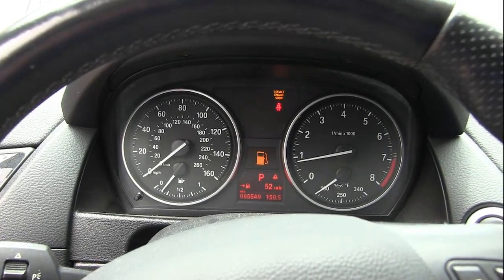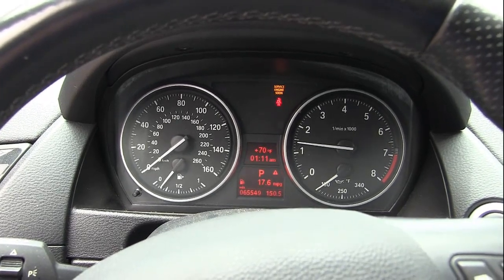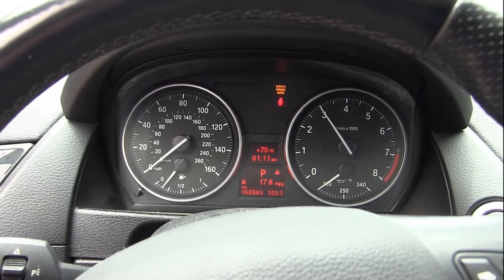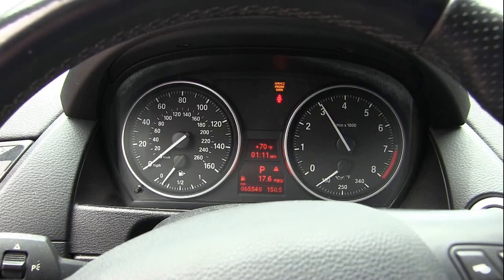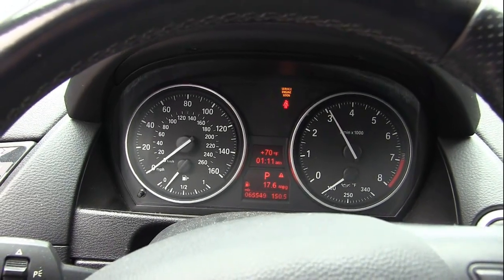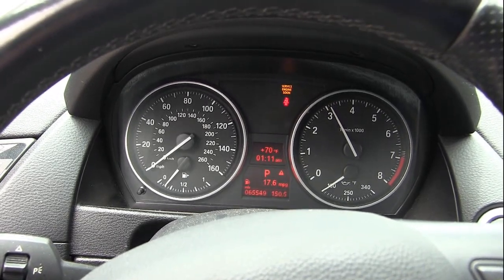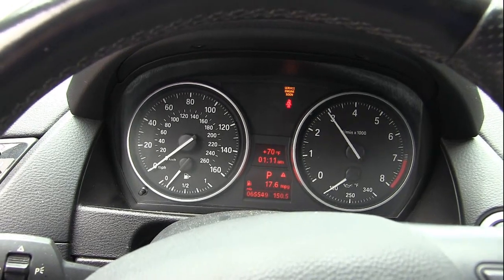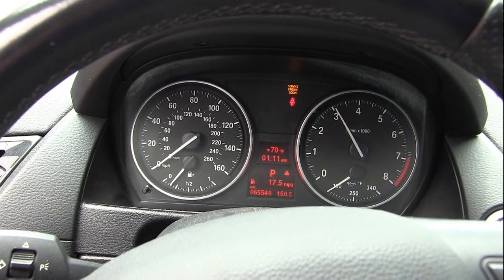Once we've started the 3C system and we're ready to clean, we want to open the throttle up and run the engine between 25 and 35 with a target at about 3,000. Every 30 seconds, the machine is going to have a rapid beep. When this beeps, let your foot off the throttle and very rapidly give a couple of throttle increases and then hold it at 3,000.